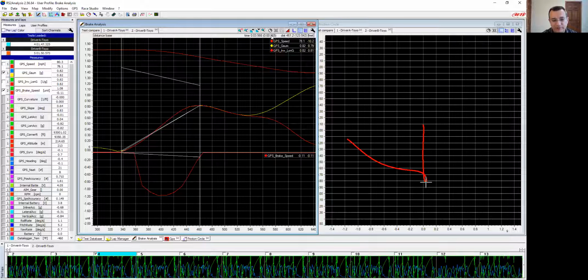And remember when we talked in previous webinars, right, the track profile, elevation, camber, those things affect these numbers as well, right? As does the track temperature, the ambient weather, the age of your tires. Those are all variables that go into this. So it's not just looking at one number, but certainly within a given session here, we should be able to see some comparison between when you're doing it well and when you're not doing it well, and try and move that brake marker back to the point at which you're not getting a dip, where you're having to ease off the brakes before you're ready to turn in because you're not quite to your turning point yet. Very good.